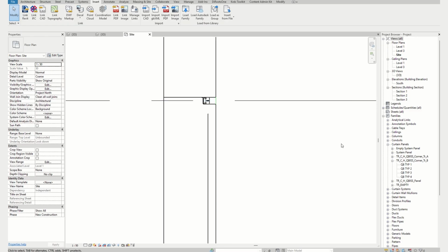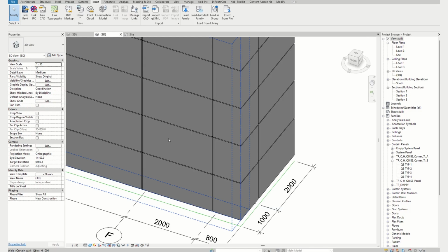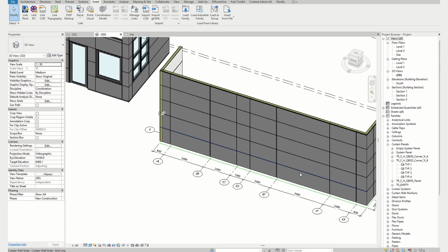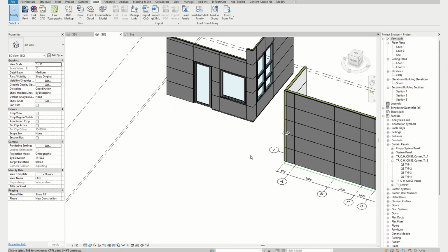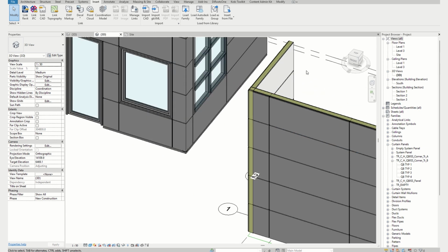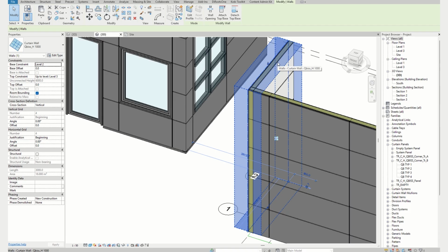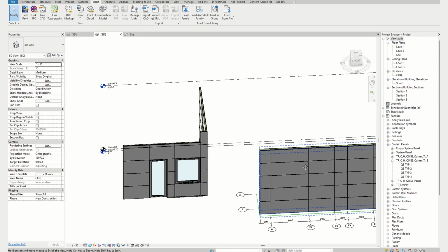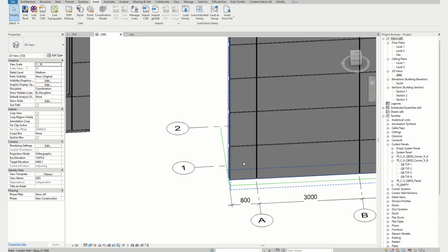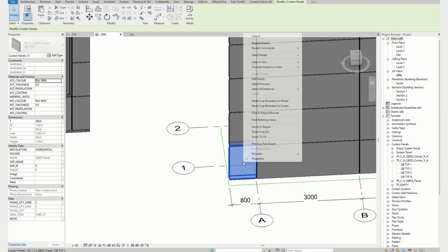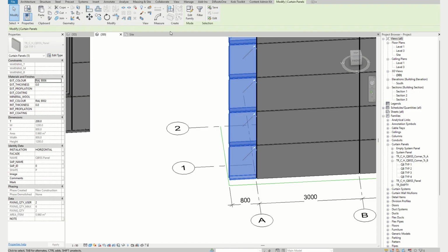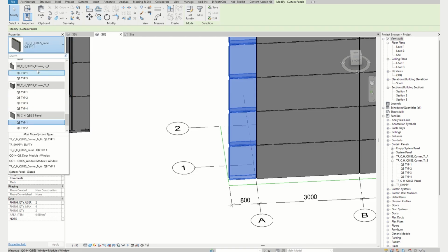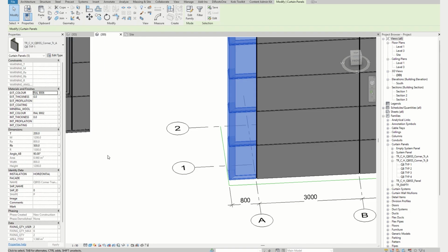And on the left side of the building, we will have side A to be part of the facade. Yes, exactly. We will replace the entire left facade column with corner elements. So let me just delete this left facade and select this column of the panels, unpin them and replace them with the side A variant.